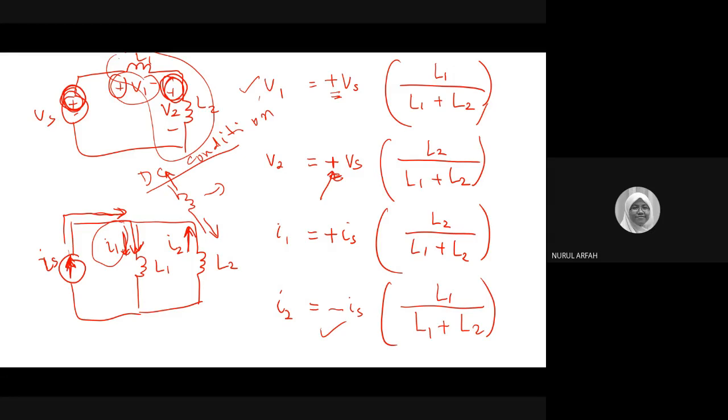Pull them apart and then you will have a short circuit. So even though the inductor is still physically there, under DC condition it behaves like a short circuit. And then the current is still there, so you need to write down the current for the inductor like this. You replace it with a short circuit and then you write down IL.